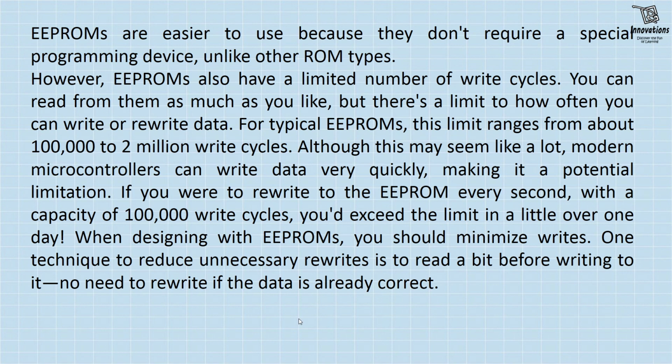However, EEPROMs also have a limited number of write cycles. You can read from them as much as you like, but there is a limit to how often you can write or rewrite data. For typical EEPROMs, this limit ranges from about 100,000 to 2 million write cycles. Although this may seem like a lot, modern microcontrollers can write data very quickly, making it a potential limitation.